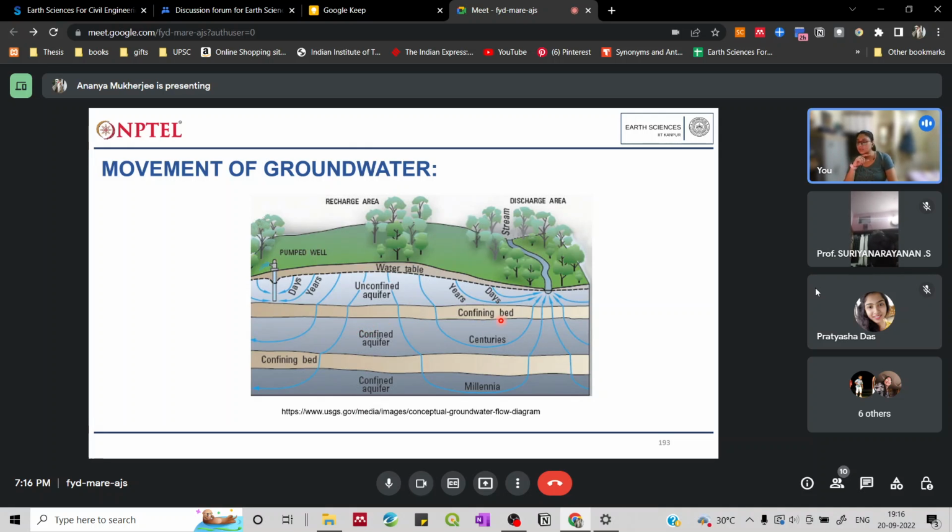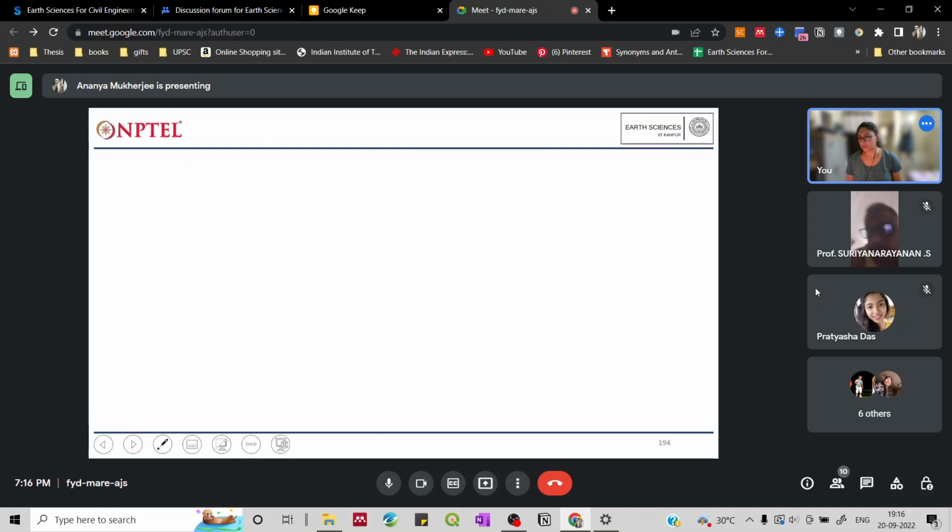That is why we need to understand the water table, how the groundwater is recharging over there, and what the sources for recharging are. Also, while building, we have to understand how groundwater can affect the foundation of our infrastructures. These things are very necessary, and for that we have to know the basics, and understand how the groundwater at a particular area is working over there.